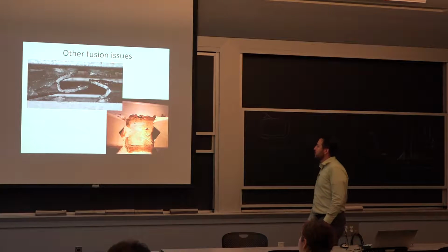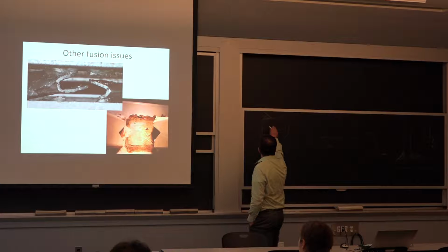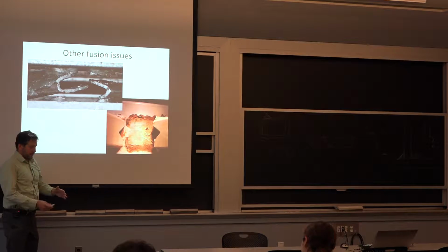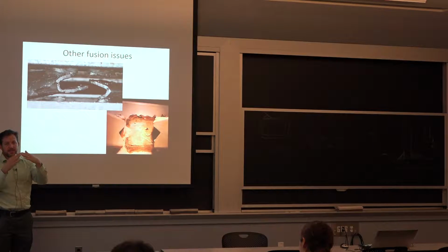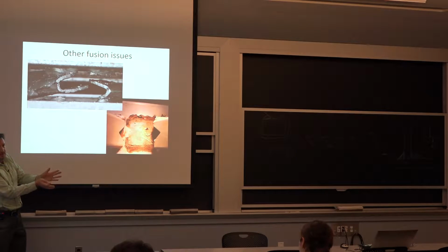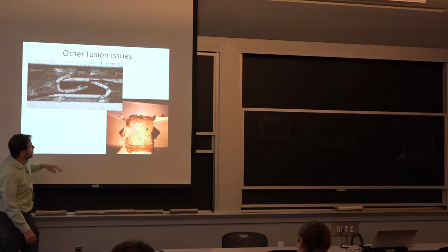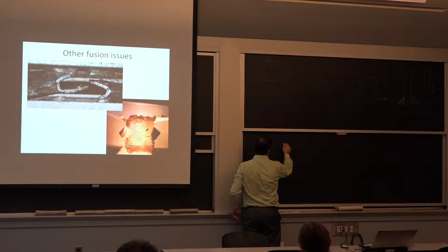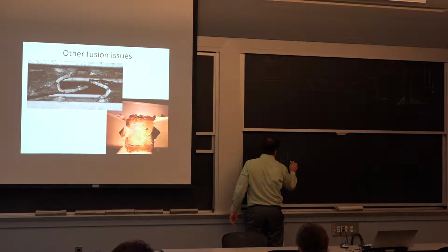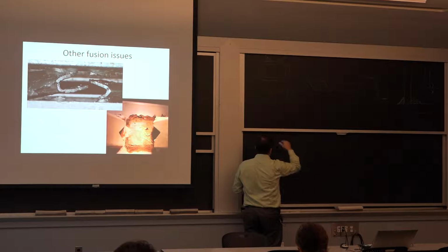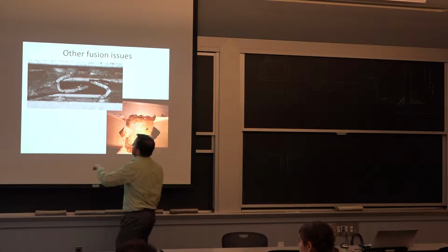I have other examples because I don't want you to think that the joists are all made this way. So here we essentially have an angle, a flat piece of steel that is bent 90 degrees, and it's crimped a little bit near the end. So instead of being 90 degrees here, it's squeezed a little further to fit between two other angles. That's actually right now one of the most prevalent designs for joists. So it will look like this. You have an angle here, you have another angle here, and then you squeeze in the diagonal. So this is the lower chord, and you have an upper chord. What you're looking at here is this diagonal.